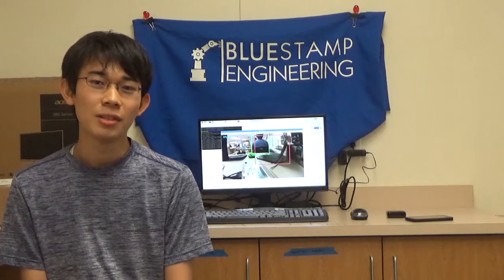The object detection that takes place in my setup is somewhat complicated. First, the Python file takes in an image from the Pi camera to process. Then protobuf and TensorFlow are used to communicate the tensors on that image to the model. The model then returns a confidence value which shows how confident the model is that some part of the image is an object.